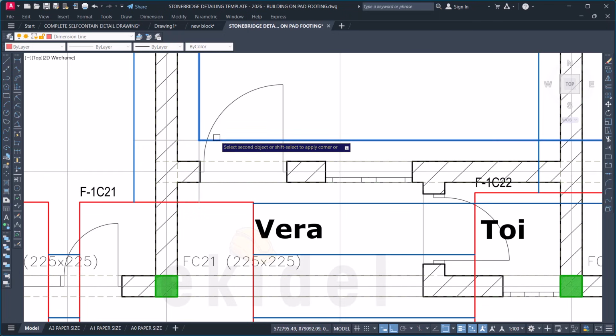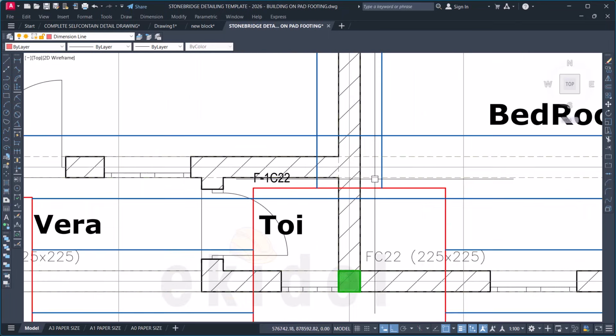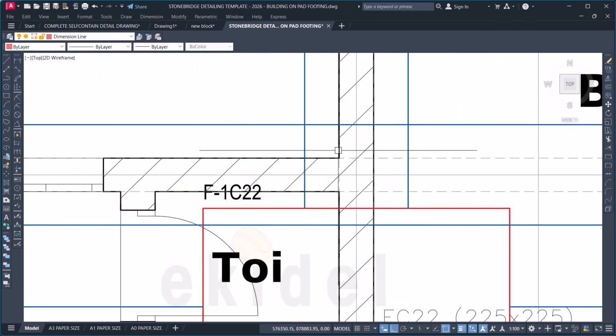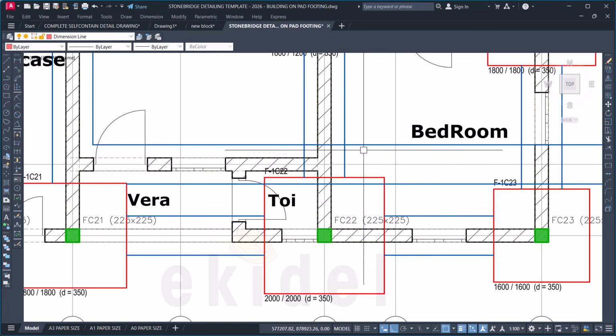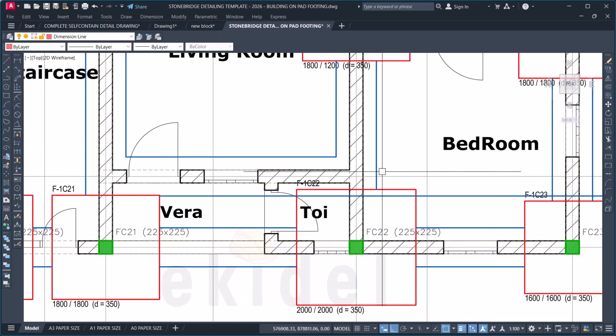click here and then click here. We have that. Okay, we have this, and again we then come here, click on this wall here, TR, enter, trim off this wall and this wall, and again we don't have anything going here, so this wall stops here, so the digging tool also stops there. So F, enter, click here and then click here. That's fine. So we then have this.